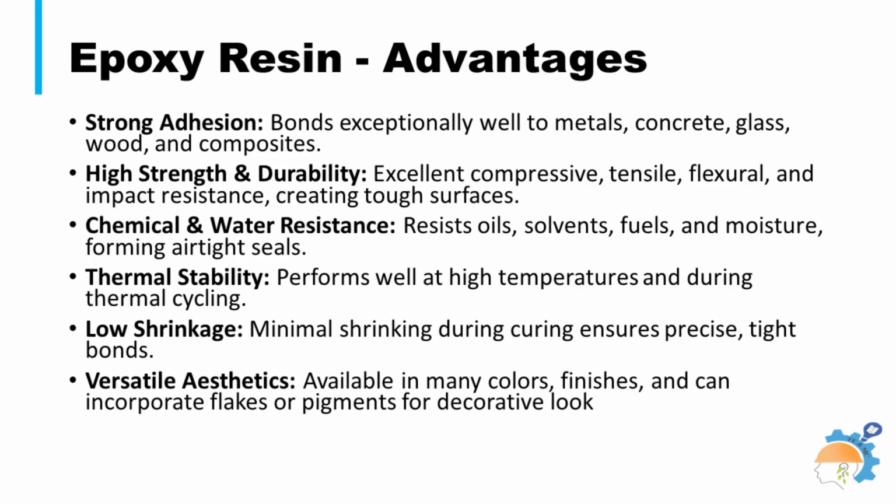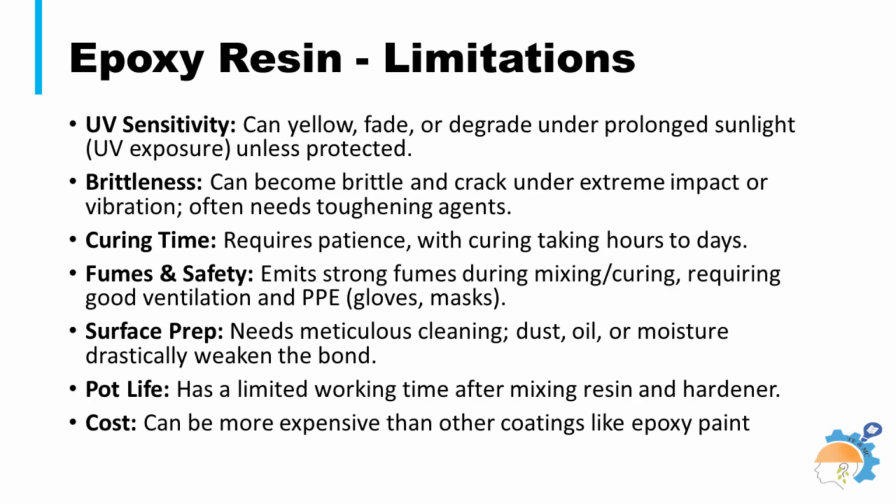Epoxy resin offers excellent advantages like superior adhesion, high strength, chemical and water resistance, and durability, making it great for coatings, adhesives, and composites. It has limitations including brittleness and UV sensitivity, causing yellowing of cured surfaces with time. It has long cure times, generating strong fumes during application. Special surface preparation procedures are essential while using this resin.